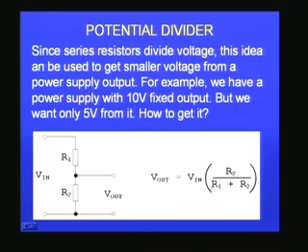The equation that I have shown here is V output is V in multiplied by R2 divided by R1 plus R2, which is a very simple relationship which you can obtain from Ohm's law. But the point I want to tell you is, when I have a load or some circuit connected across the output of R2, the current for this circuit will have to come from your main power supply, which is V in, through the resistor R1 also.